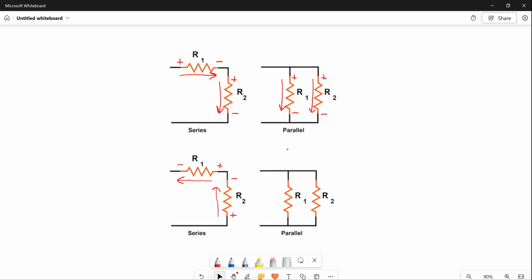Over here on the bottom right circuit, let's do the same thing there. Let's show the current going up there. And just for the heck of it, let's show the current going down here. Now, that can't happen because of the node voltages, but you'll just get a negative answer. You can assign direction any way you want. It's arbitrary. Put a positive down here as soon as you draw the arrow and a negative up there, and put a plus up here and put a negative down there. That is called the passive sign convention. It'll always work out for you. Let's continue on.